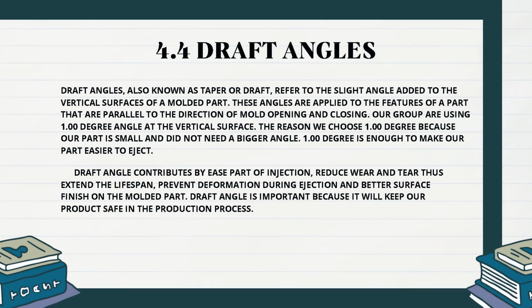Draft angles. Draft angles, also known as taper or draft, refer to the slight angles added to the vertical surface of a molded part. These angles are applied to the features of a part that are parallel to the direction of mold opening and closing. Our group is using 1 degree angles at the vertical surface. The reason we chose 1 degree is because our part is small and did not need a bigger angle. 1 degree is enough to make our part easier to eject.